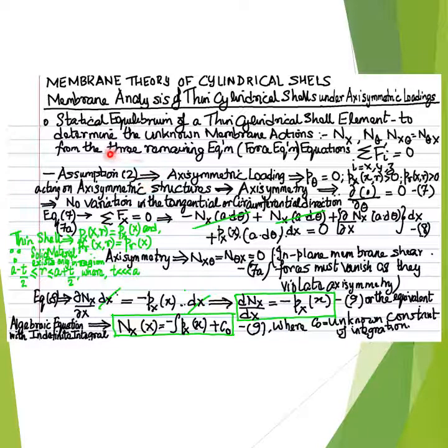The assumption number 2 is therefore not only necessary but also relevant to complete the membrane solution of the thin cylindrical shells, that is, the membrane analysis of thin cylindrical shells in order to solve for the unknown internal in-plane or membrane actions nx, n theta and nx theta.